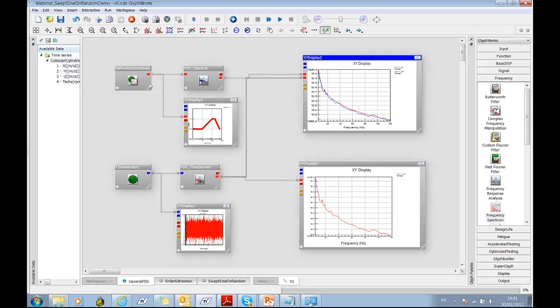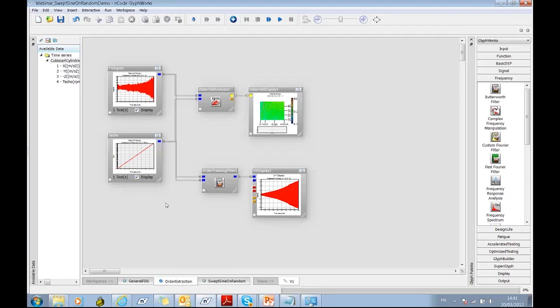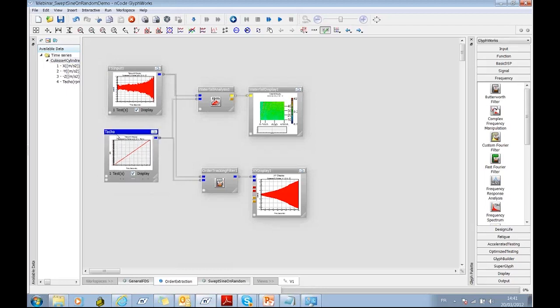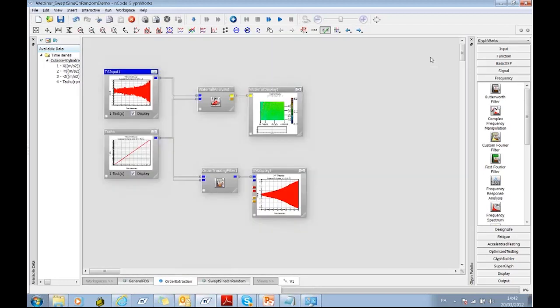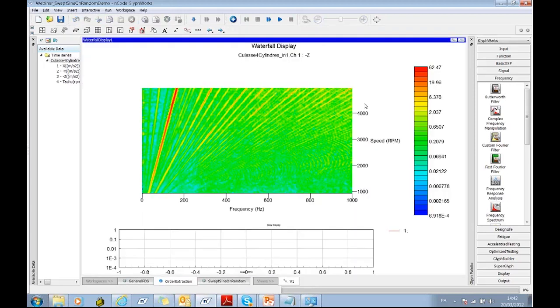and analysis. We mentioned order extraction. So now the input signals, for instance, are an RPM signal and a vibration signal in acceleration, right, coming from a run-up test. We do a waterfall analysis to look at the waterfall plots, Campbell diagram, and here we see beautiful orders popping up from this spectrogram. We can ask for the order to be displayed underneath.